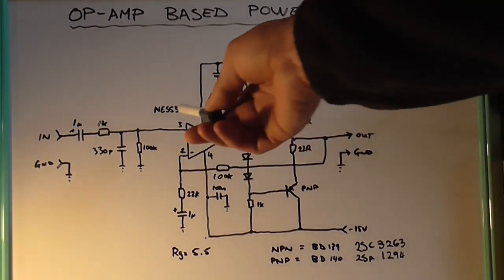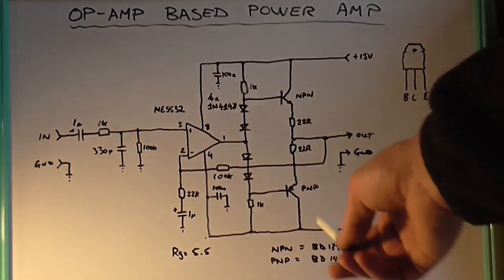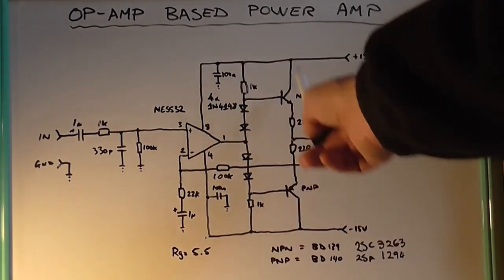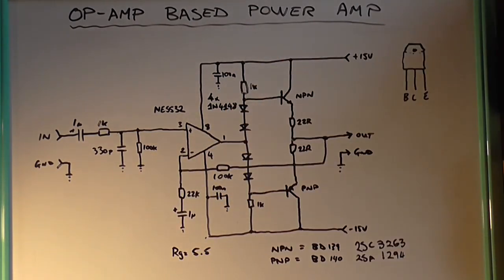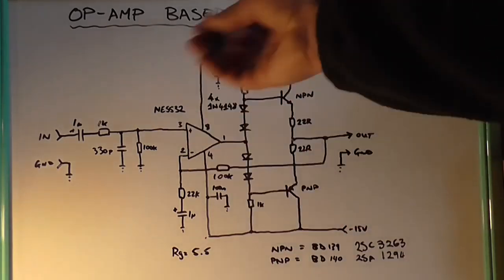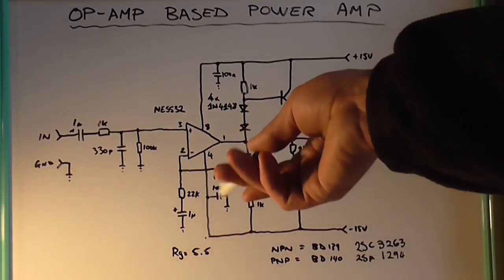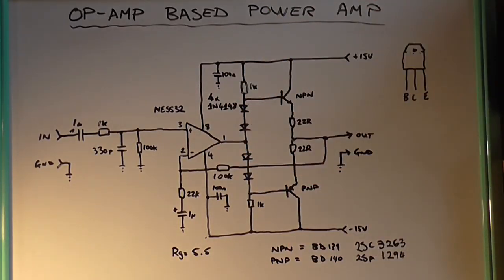And because this is an NE5532, a dual OpAmp, you can use the other channel of the OpAmp and a secondary output stage there to drive the right hand channel. But in its current configuration, it works fine, and it may become a circuit that I'll use somewhere else later along the line, because I know it works.